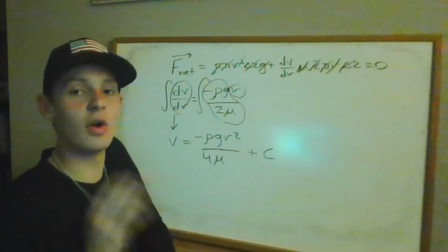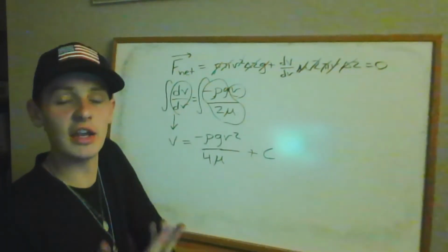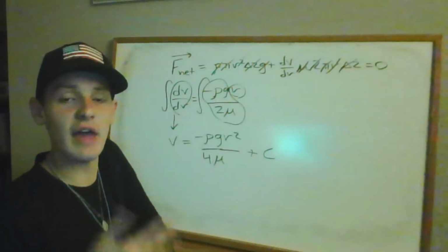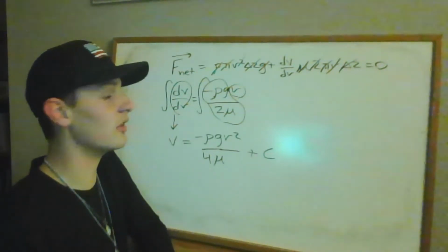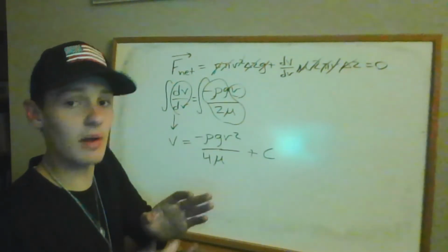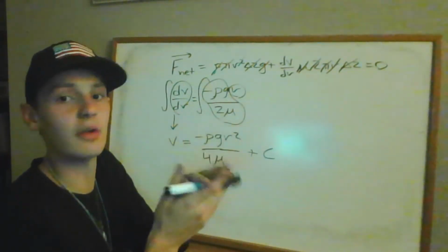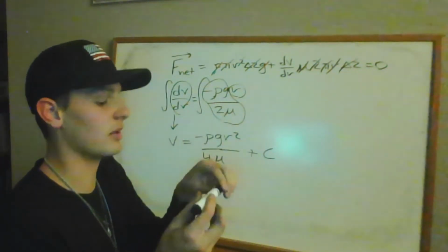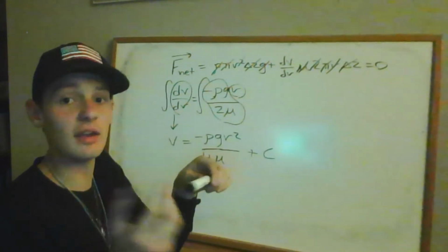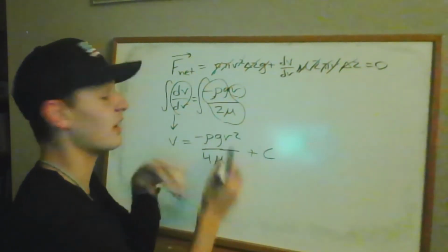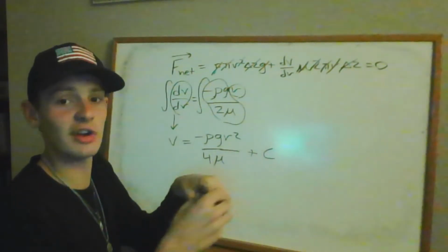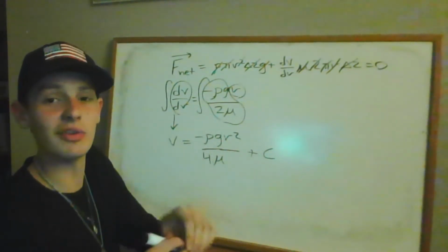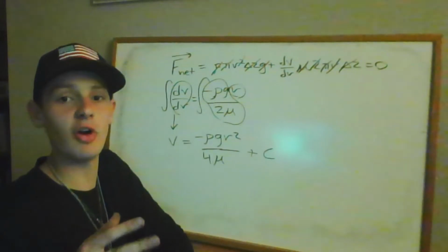This is something I wanted to mention earlier when I was talking about the shear stress due to the viscosity of our fluid, because that emanates from the contact between layers of fluid. I also talked about the difference in speed based on the radial position causing that shear stress, wherein the slower moving fluid was exerting a shear stress on the faster moving fluid within our controlled volume.